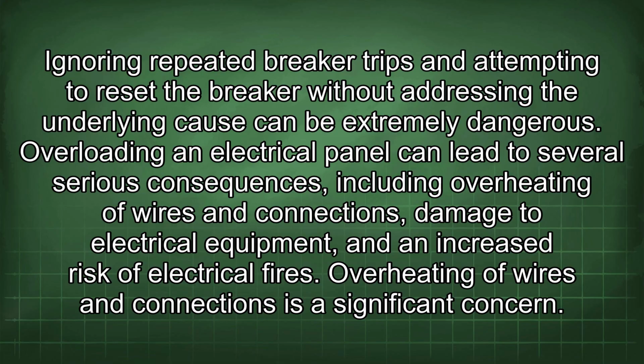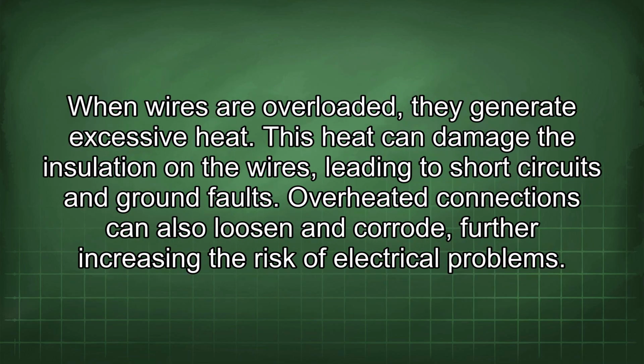Overloading an electrical panel can lead to several serious consequences, including overheating of wires and connections, damage to electrical equipment, and an increased risk of electrical fires. Overheating of wires and connections is a significant concern. When wires are overloaded, they generate excessive heat. This heat can damage the insulation on the wires, leading to short circuits and ground faults. Overheated connections can also loosen and corrode, further increasing the risk of electrical problems.